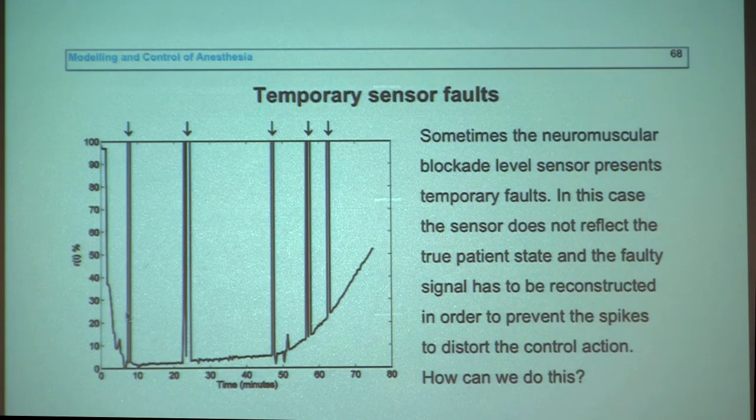This is a non-Gaussian behavior, non-Gaussian noise, heavy tails. Okay, so one thing that you can do is you replace your quadratic criteria by a linear criteria, and then the optimum estimator is no longer the average, but it's the median. Okay, so use a median filter.